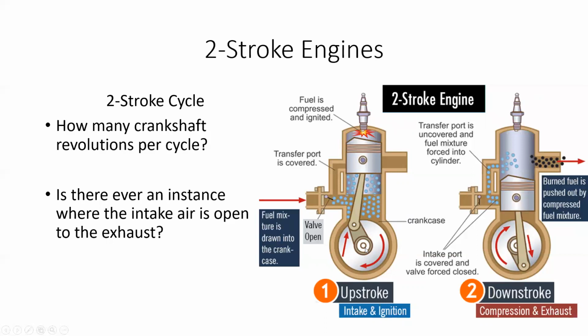There's the crankshaft and connecting rod, and all these bearings see a lot of revolutions. If that was just metal on metal, it wouldn't last very long. It has to be lubricated. But because our fuel is coming in through here, we can't have an oil bath down here that this is sloshing around in, because that would arbitrarily mix oil into the fuel.